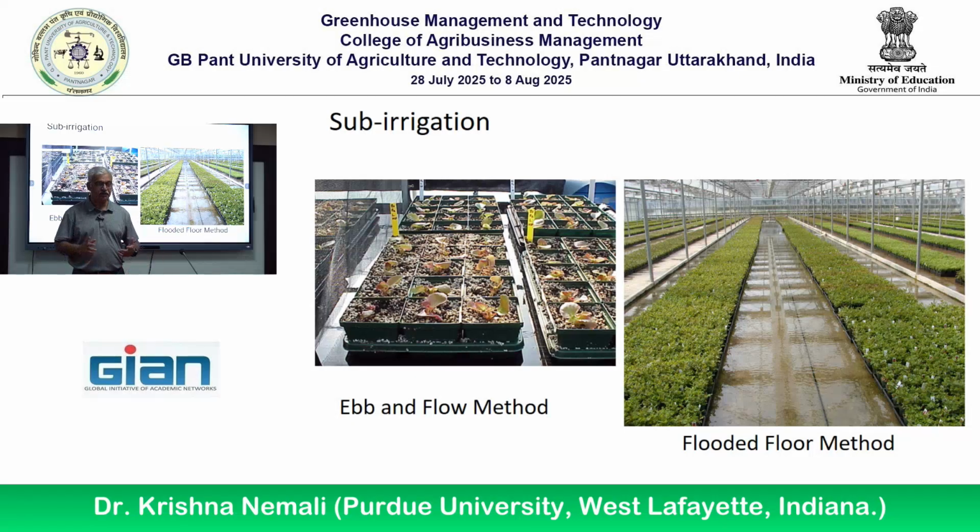If it is a dry substrate, it takes a lot of water through sub irrigation. If it is a wet substrate, it takes less water. But at the end of the day, all parts will have similar water content. Remember uniformity. Here is a uniform situation, and you have done a uniform irrigation completely automatically, simply through using physics.